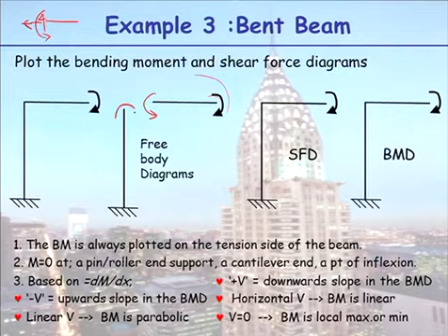So the moment here I would draw as equal and opposite on the other side of my cut, and therefore that reaction moment must be anti-clockwise, which it would be to oppose the clockwise deflected shape. Yep, good.